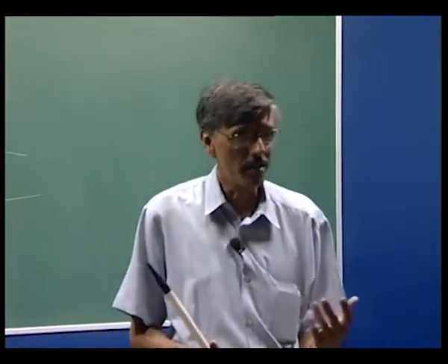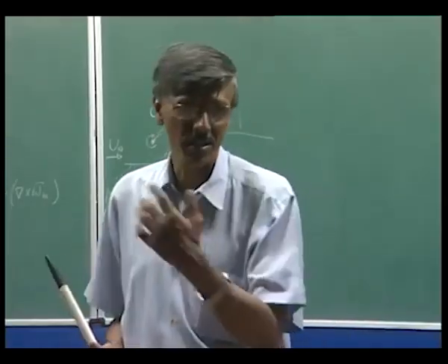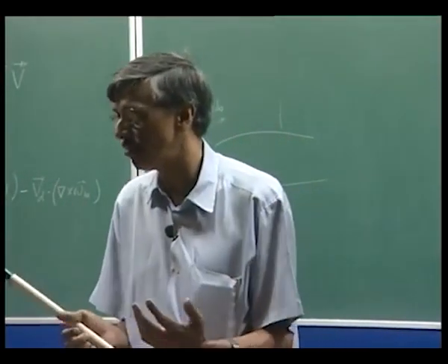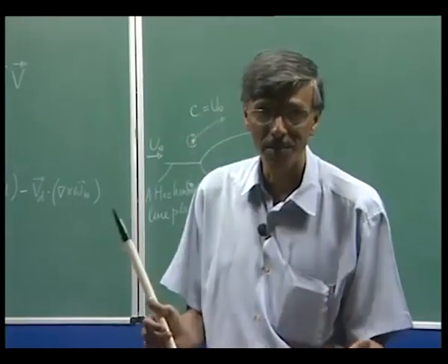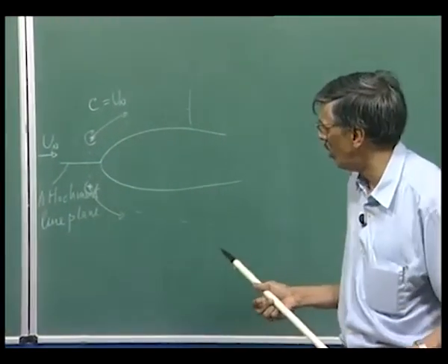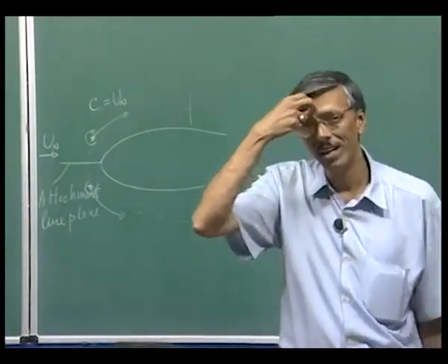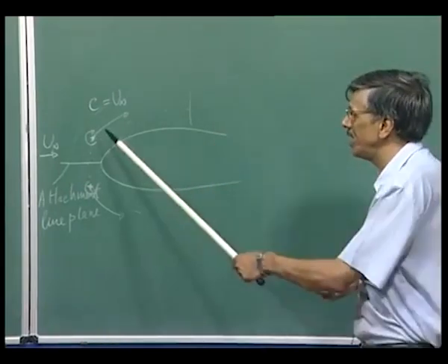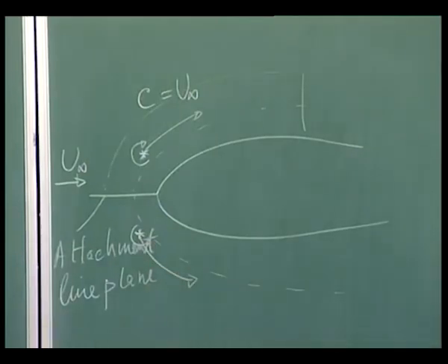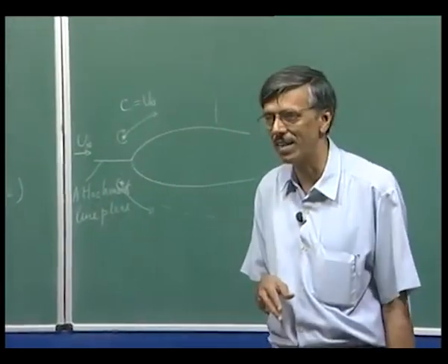And over the wing, then you are basically talking about both mechanisms being present. So, we are talking about if there is a streamwise instability, if there is a cross flow instability, or a combination of the two, everything should be picked up by a three dimensional direct simulation of such a flow. So, that was perhaps attempted by Obrist and Schmidt, but they did not see any effect of it. Probably they did not also study what happens in the attachment line. Maybe their attachment line flow was completely quiet. There was no unsteadiness in there.